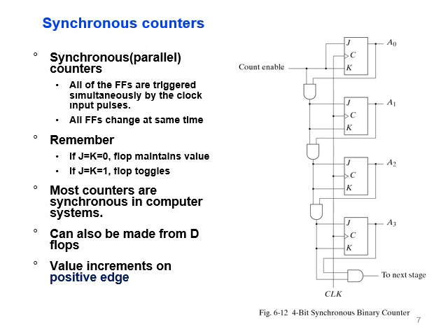Now let's come to the synchronous counter. Synchronous counter, from the name, it's working simultaneously, in synchronism. Now as you can see here, this is also J and K, with counter enable. Coming here, you can see J and K together. This is the clock for all of them, coming from here. And the output is taken now to an AND gate with the counter enable to be input for the next flip-flop, and going as input to the next AND with the output of the second flip-flop, which produces output which comes to the next AND with the output of the next flip-flop, and so on until we get here, and which go for the next higher steps.